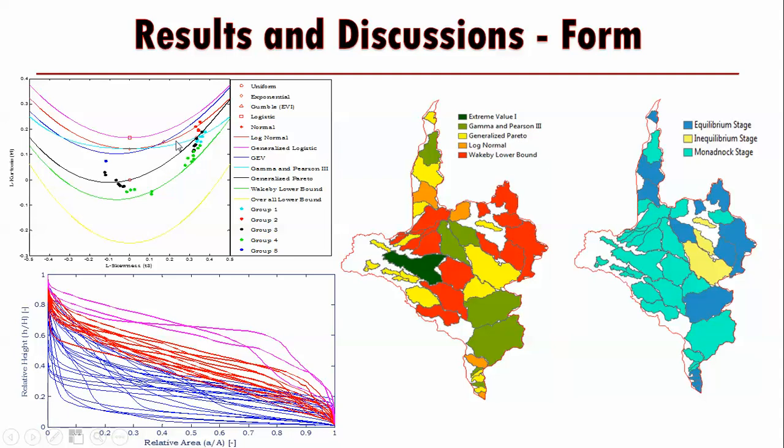You have to plot the kurtosis and the skewness of your station over these distribution types. The point to which your site or river kurtosis-skewness plot gets closer will be the distribution type for that particular watershed.